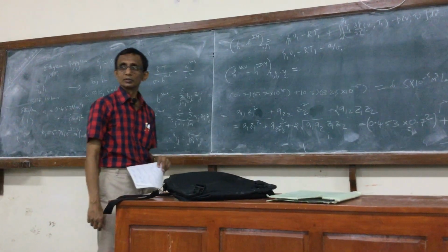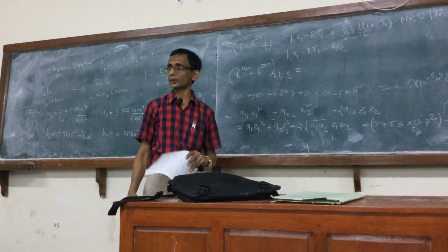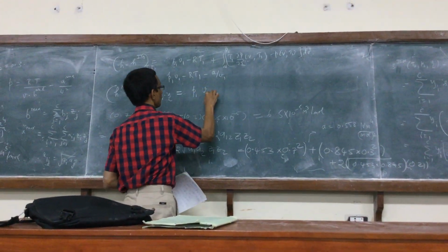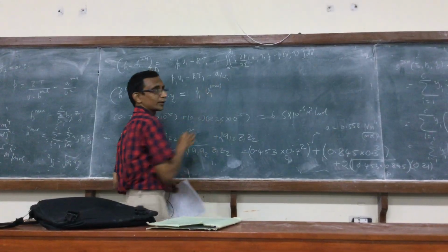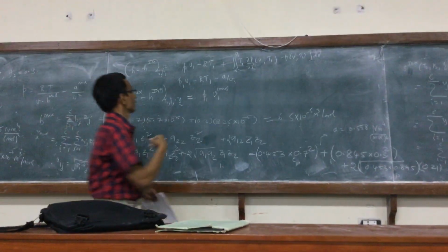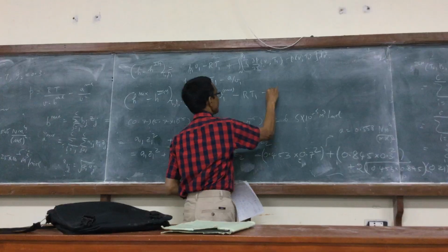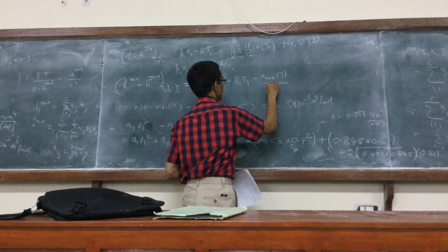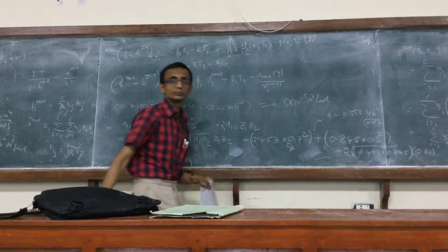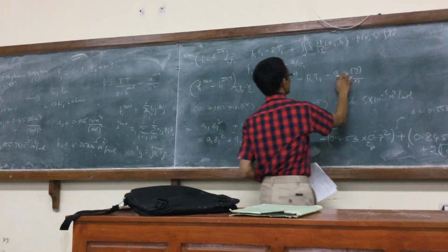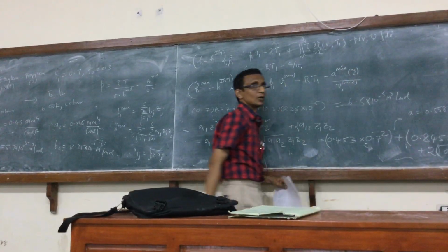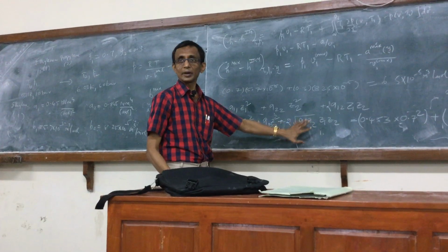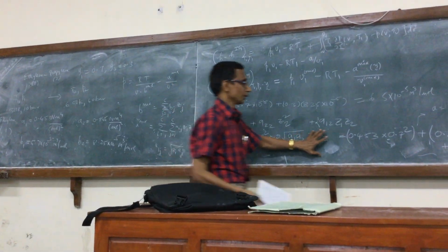For a particular mole fraction, I'm not going to put a superscript or subscript on that one, any mole fraction. That would be P1, same formula, P1. Now, just to ensure that you understand, this is now going to be the volume of the mixture, minus R T1 minus A mix, which is of course a function of y. This is what you have calculated actually, A mix, because the composition is remaining the same. So for both states this A mix would work.